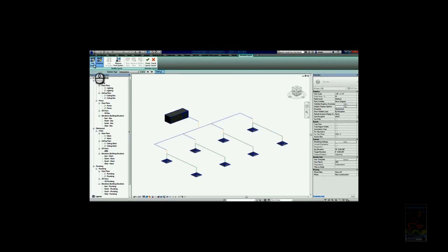Now, if you need to edit the layout, you can click Edit Layout, and you can pick a particular line, and you'll see that's at 11, that's at 11. That one's tied back to the unit, so whatever the height for that unit is, I'm thinking it's 12 feet. This one's set to 10 feet. And so if I need to adjust these to be just as high as those, I can just type in 11 and bring them up.